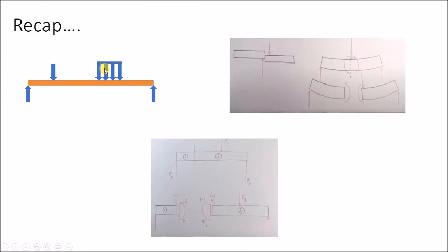So to recap, we have a beam simply supported at both ends, here and here. Beams are subject to carry loads, and forces will act upon them. We can have a concentrated load which acts over a very small area of the beam, or a distributed load that acts over a larger span of the beam, so the weight is distributed along a wider area of the beam. And the two ends that sit on supports for this simply supported beam are considered upward reaction forces.